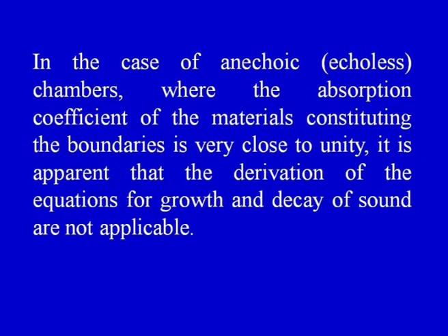Now, in the case of anechoic, that is echoless chambers, where the absorption coefficient of the materials constituting the boundaries is very close to unity, very good absorbers, it is apparent that the derivation of the equation for growth and decay of sound is not applicable.